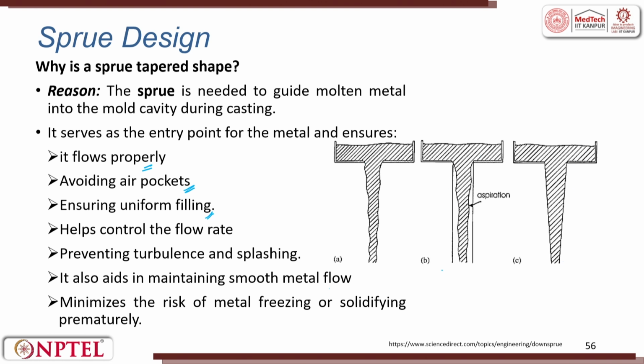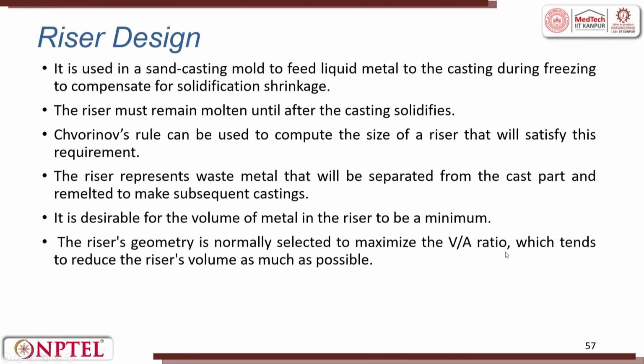Is that clear? If you have a parallel one, the air can go inside and then it can fill here. So, the solidification will happen. Slowly, this will get closed. So, if the distance is long, at some point of time both sides will meet and you will have a shut of the flow happening. So, that is why we always try to keep the sprue tapered.